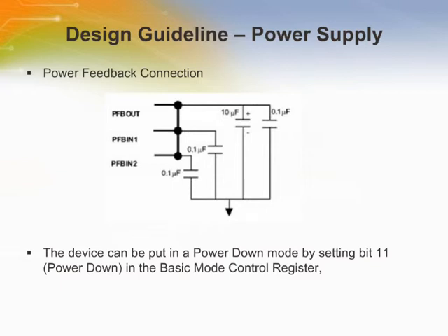A 10 microfarad tantalum capacitor in parallel with a 0.1 microfarad capacitor should be placed close to the PFBOUT pin, and a 0.1 microfarad capacitor should be as close as possible to the PFBIN1 and PFBIN2 pins.